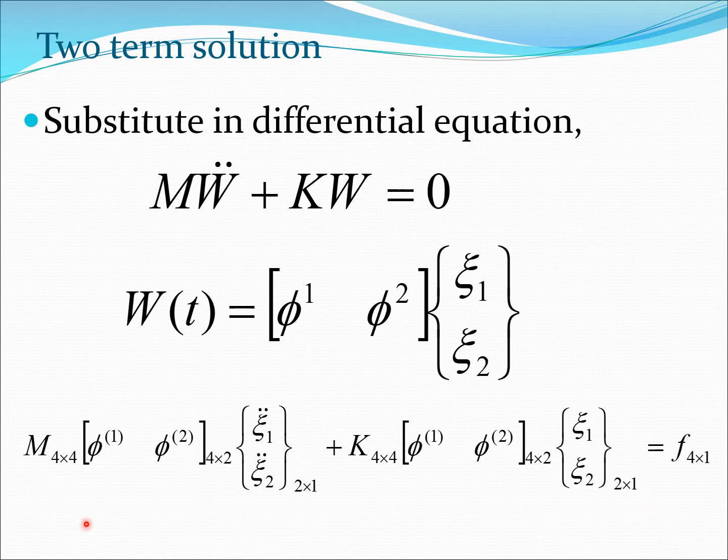Now looking carefully, you can see a lot of the things in terms of the dimensions here. So the mass matrix would be 4x4, as would the stiffness matrix. Force vector would be a 4x1. But here I am considering these two matrices here. So essentially this modal degree of freedom is a 2x1 system because there are only 2, and this phi1 and phi2 are 4x2 systems because each of these has 4 rows because there are 4 degrees of freedom, and of course there are 2 of these columns, so this is a 4x2 system.